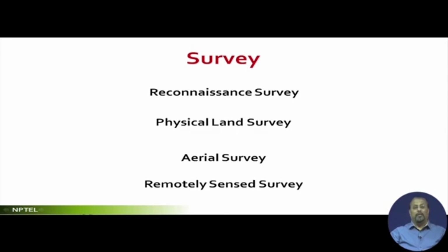Nowadays aerial survey is best represented by the Google Maps that you have seen. Google Map is a true representation of the aerial survey. If you scroll down and further down, the height between the surface and your camera reduces, more details are seen, and you can comprehend better. This comprehension was earlier given by the aerial survey. In this survey, if an object is obstructing the visibility of another object at a lower level, then that particular detail is lost.